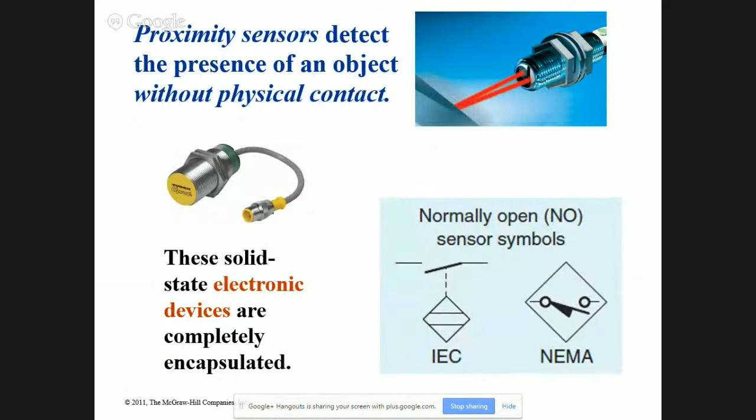Here we have sensors. What does the square mean around a limit switch? And what does that square mean when you see that diamond? The diamond. Totally forgot. That means it's a semiconductor. It's an electronic switch of some sort, and it's got the little diamond around it.